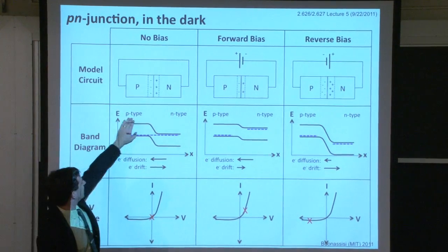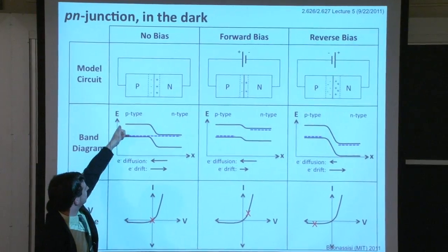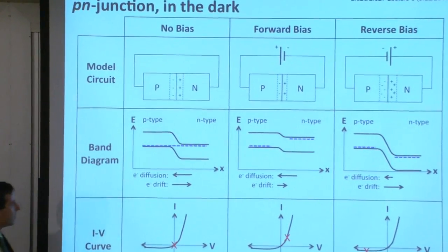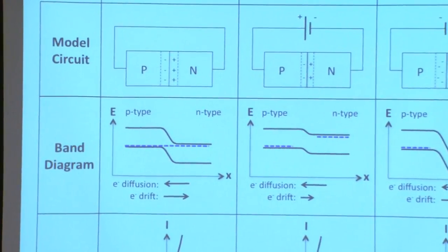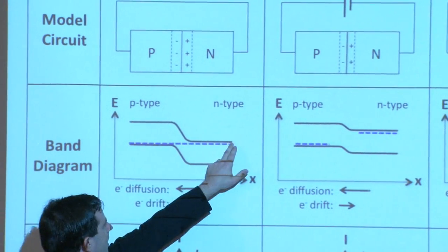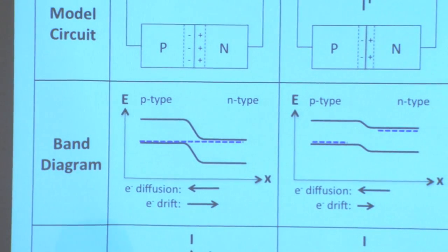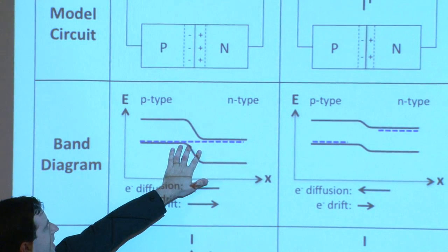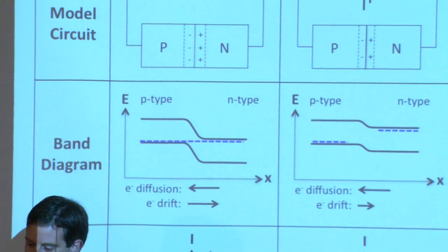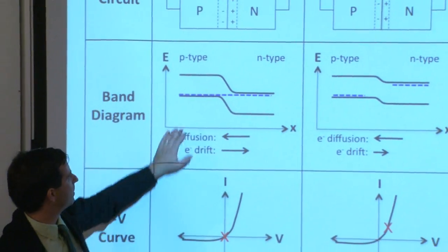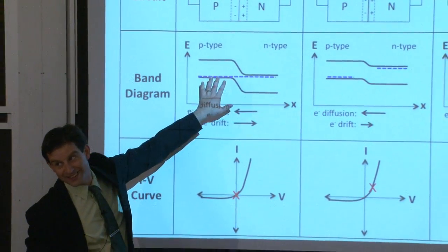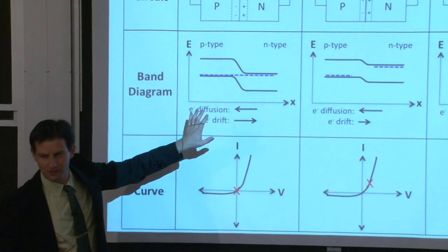Now we have the energy band diagram shown right here, where this dashed blue line represents the chemical potential, also called the Fermi energy, throughout the entire device right here in cross-section. And just to be very, very clear, we've so far described the solar cell as light coming in through the top. And now we've rotated this structure by 90 degrees to represent the pn-junction. That's been a little confusing for some folks.